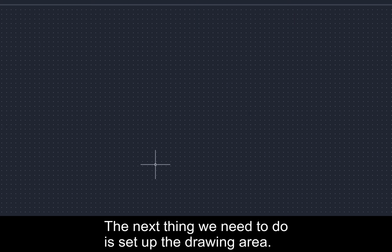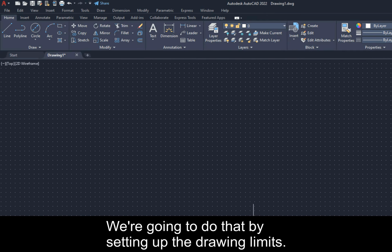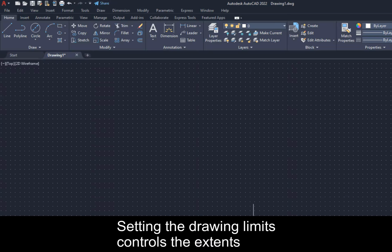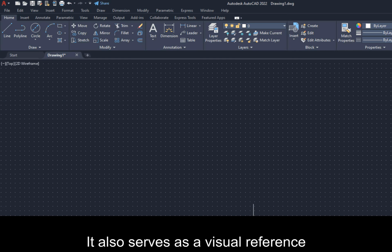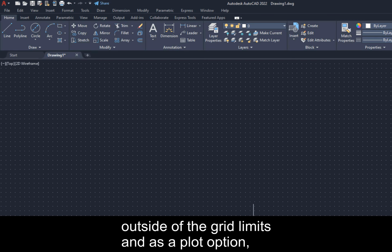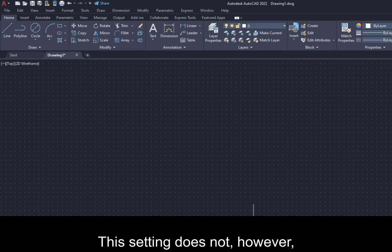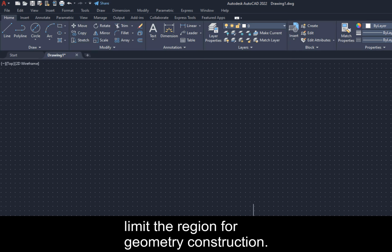The next thing we need to do is set up the drawing area. We're going to do that by setting up the drawing limits. Setting the drawing limits controls the extents of the display of the grid. It also serves as a visual reference that marks the working area. It can also be used to prevent construction outside of the grid limits and as a plot option that defines an area to be plotted or printed. This setting does not, however, limit the region for geometry construction.